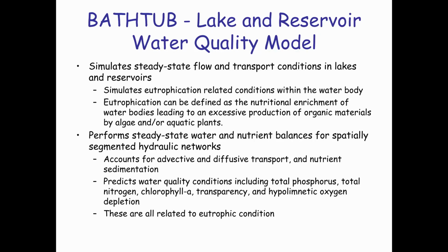I might also mention that on that slide it was stated that the model simulates steady state flow and transport conditions. It actually does allow you to look at transient changes in water storage or lake water level. Generally, the model is used for situations where the water level doesn't change over time, but the model does allow the condition where the lake water level is changing over time, which would imply not a steady state, but a transient flow condition.